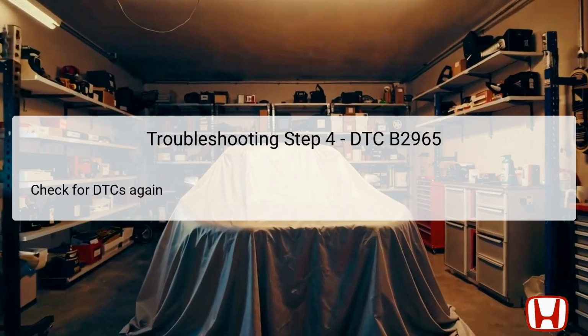After conducting the self-diagnostic function, the technician must check for DTCs again. This crucial step ensures that any new or reoccurring codes are noted, particularly focusing on DTC B2965. If the fault code reappears, it indicates that the communication failure persists, warranting further diagnostic steps. If no DTCs are present, it could suggest an intermittent issue, often related to loose connections or wiring faults. Properly recording this information is key for advancing to the next steps in diagnosing the issue thoroughly.